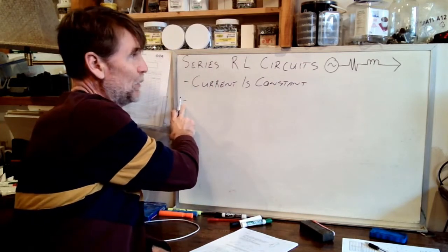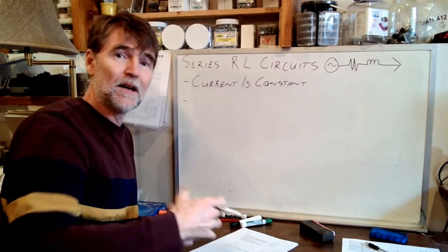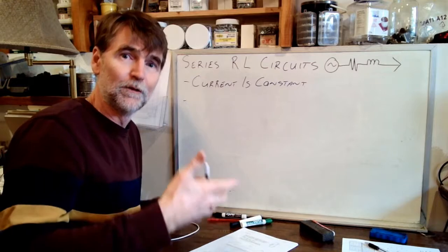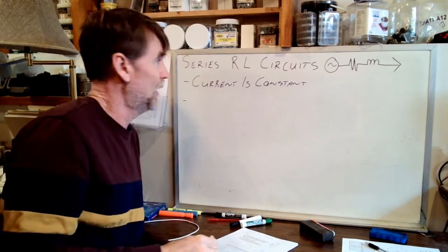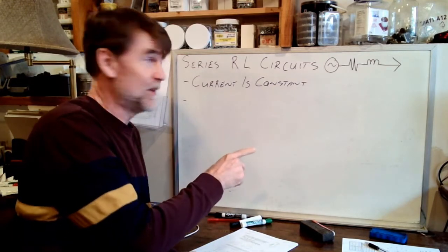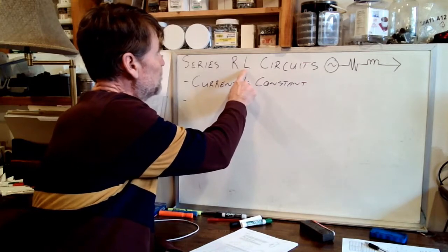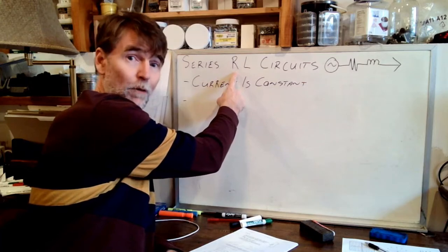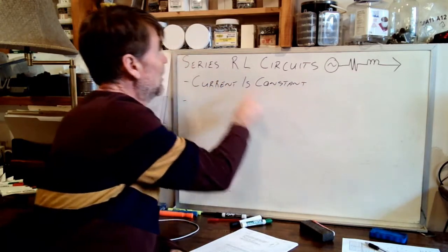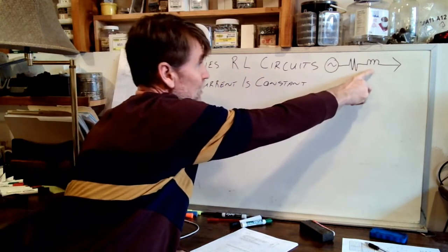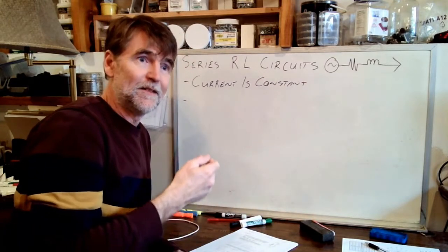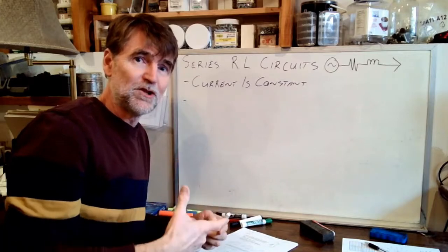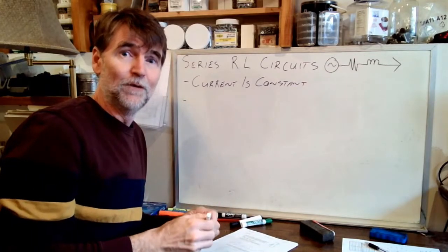The second point that we want to focus on is what kind of loads do we have in our circuit? And so what is our current to voltage relationship? Okay? So this goes back to the first video this week, where we talked about the fact that, I should mention this, series RL. So R is for a resistor, there it is, and L is for an inductor. So there it is. So what is it about the inductor that we just learned when we talk about the relationship between current and voltage?